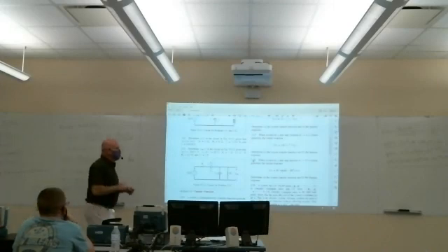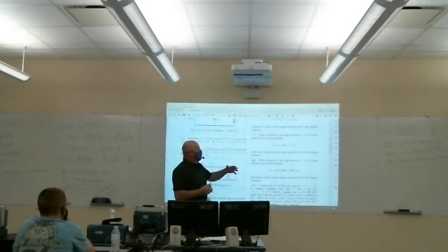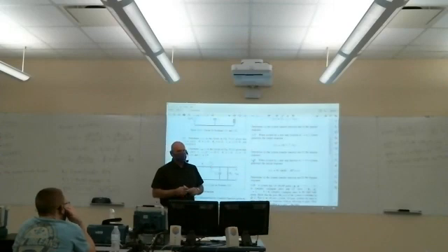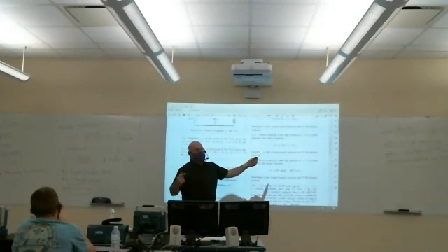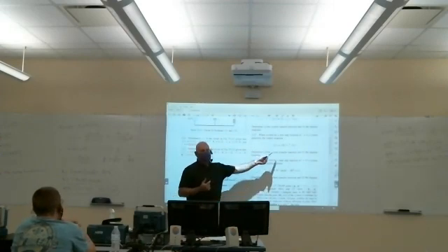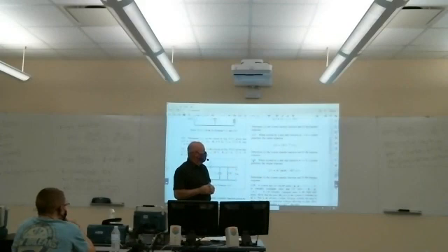So this is an example of that type of problem. They give us the output when the input's a unit step. So it's not an impulse, and this is not the impulse response. This is the step response. We actually did have a way to get the impulse response from the step response. If you recall, taking the derivative of this would give us the h of t. But let's assume we don't know that. Could we get the transfer function using Laplace transforms? How would we do that?